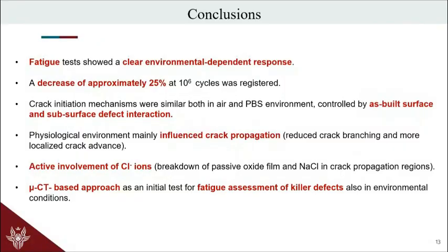And with this, I would just like to conclude, wrapping up. We can see a decrease of about 25% at 10^5 to 10^6 cycles for the fatigue tested specimens, mainly associated, in my opinion, with the crack propagation part rather than the crack initiation. We also tried to develop, despite being preliminary, a micro-CT-based approach for the fatigue assessment of these killer defects.